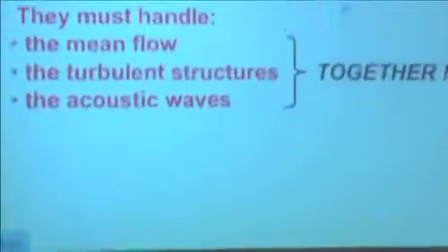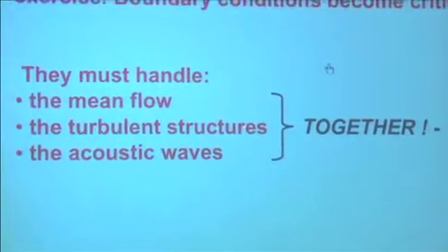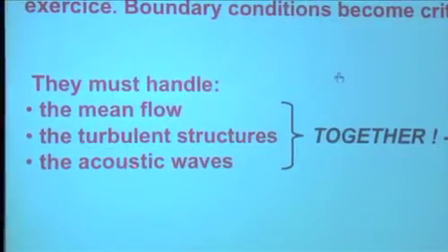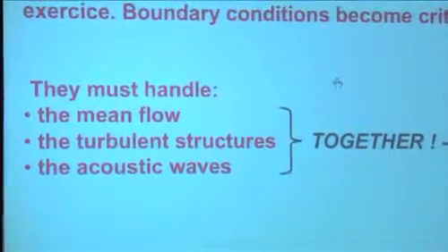It's a classical tool to manipulate acoustic waves, and I want to show you what it gives on a simple problem. If you do a compressible simulation of a combustion chamber, you must specify the mean flow at the inlet and the outlet, mean flow at the inlet basically. You must be able to inject turbulence. I'm going to do a laminar case here, so you can forget about turbulence. And you must manipulate the acoustic waves, everything together. And again, this is tough.